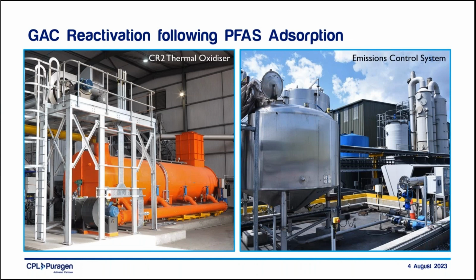Activated carbon used for the adsorption of PFAS from water has been successfully reactivated and put back into use following reactivation. It's already being done, and we're very confident in our ability to deal with the emissions arising from the carbonization and gasification of fluorinated organic compounds, including PFAS, and we have already conducted detailed work to study and confirm it.